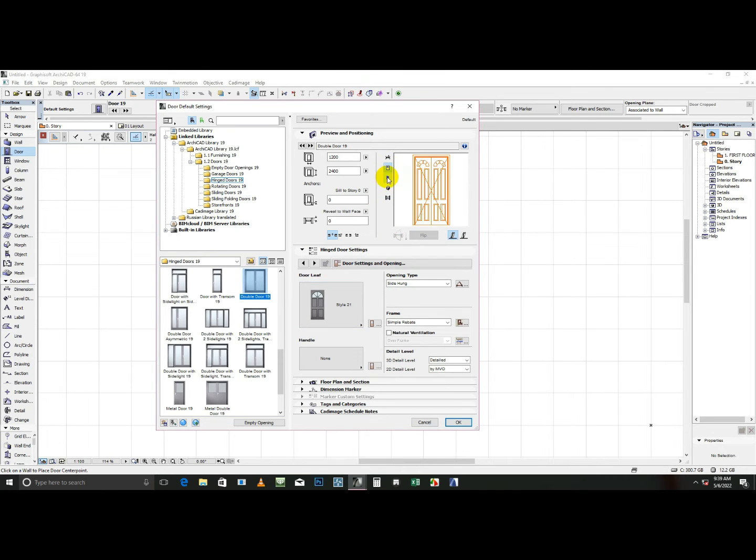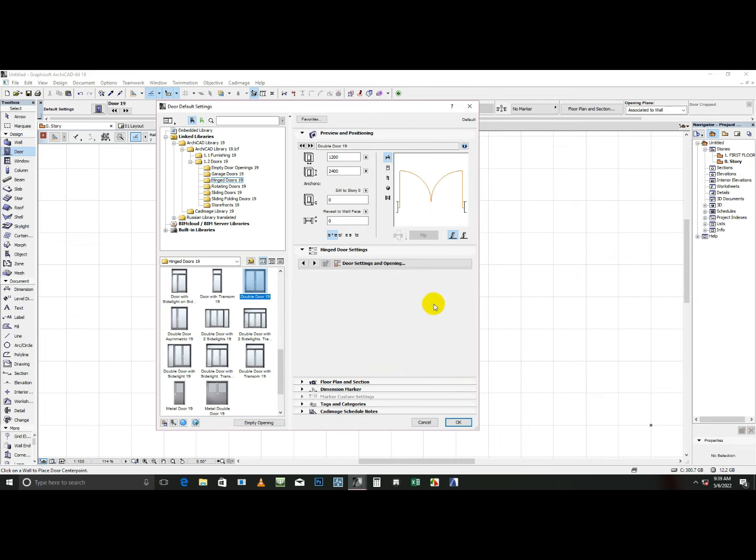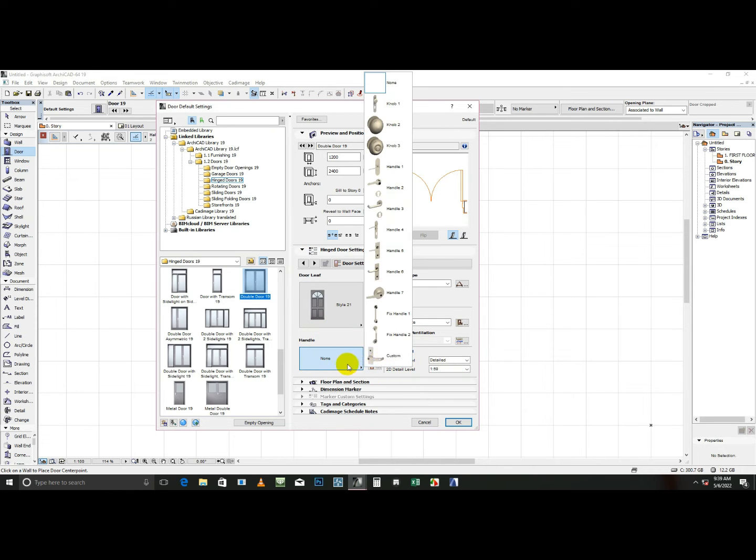If you press on this, you're going to see it's the door in different format. So it's still necessary, you go to that. I want to detail my 2D door. If I detail, you're going to see a change here. I'm using the scale 1:50. You see, my plan looks more detailed now in plan view. So I want to use a lock handle.